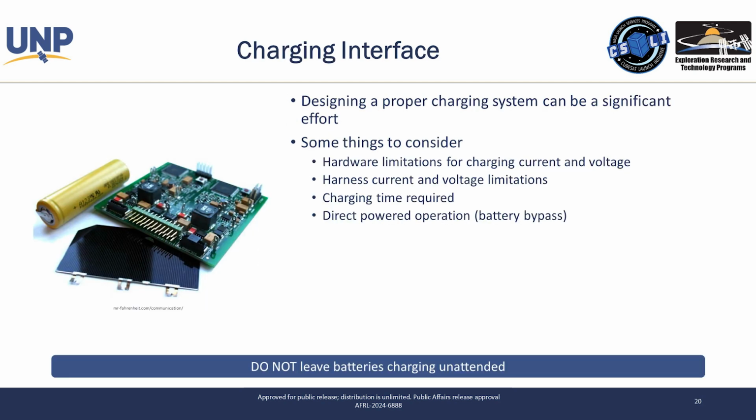For charging and discharging, we have to do that as a full up integrated test. And so we need a power port on the side that allows you to charge, discharge the batteries, monitor the batteries, maybe power things up around the inhibit switches, things like that, and make sure that your batteries are topped off, ready to launch. CubeSats are typically stored for a very long time prior to launch. So making sure you have the absolute maximum capacity in your batteries when you start, so that you'll make it through that storage period, which you will not be able to know how long that's going to be.